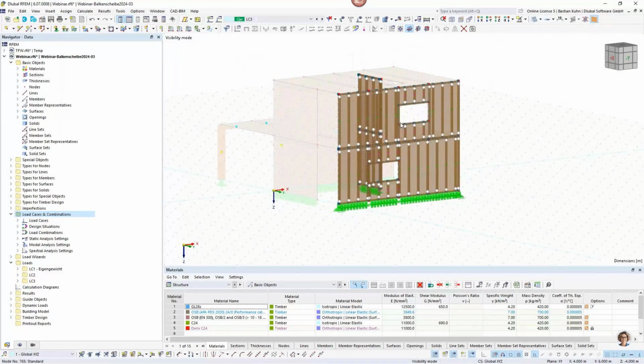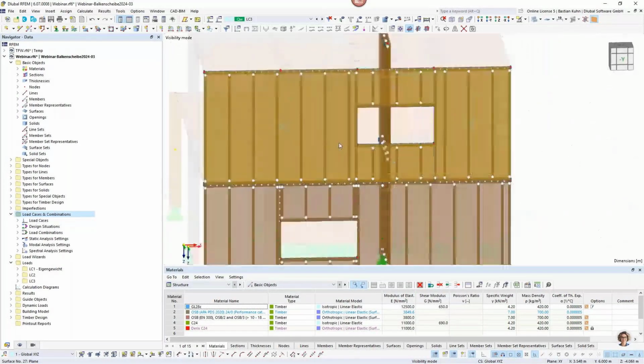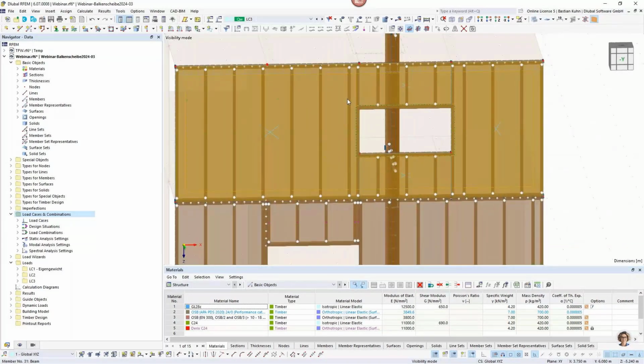But anyway, okay. So now we look at the top wall first, and we see that now the distribution of the beams and the posts is quite good. We would calculate the opening, and it kept our spacings of 625 millimeters in between, and here we have a middle value of 100 millimeters left, and this is also good because we can still get insulation into it here.